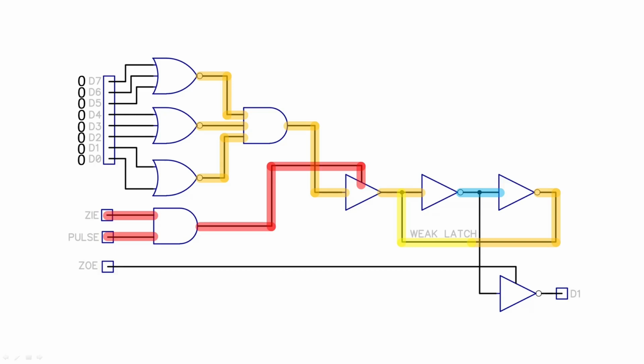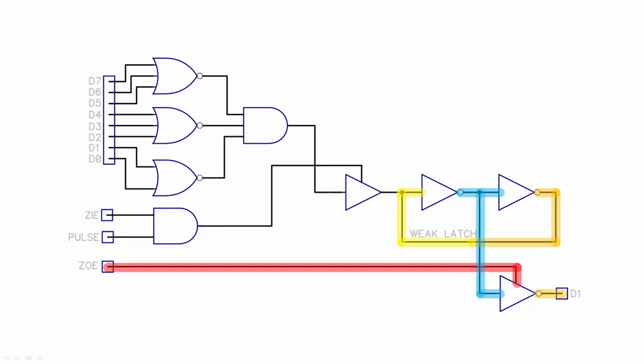Now there's an instruction called skip if 0. And what that does is it skips the program counter forwards 2 bytes if you have a 0. So with that instruction, you'd have a 0 output enable on, and the 0 flag will then get fed out to D1, not D0.